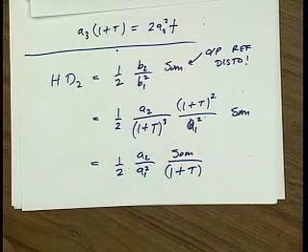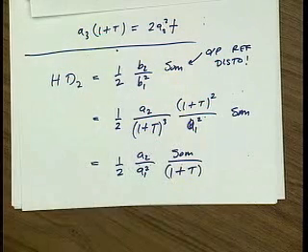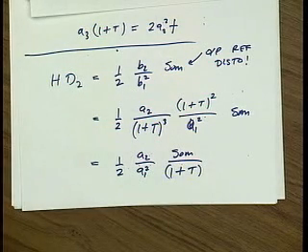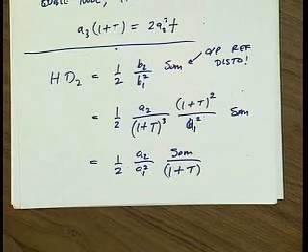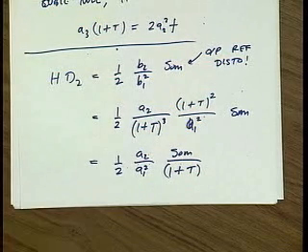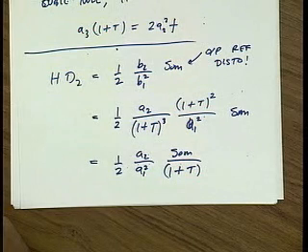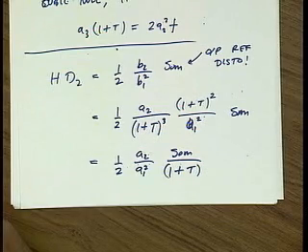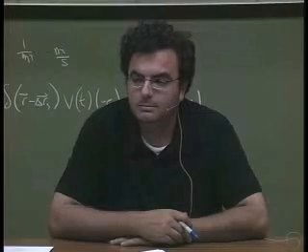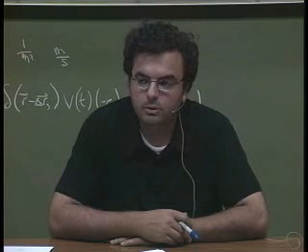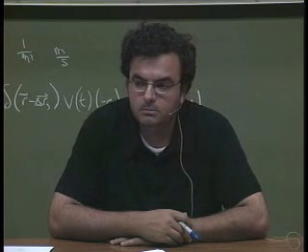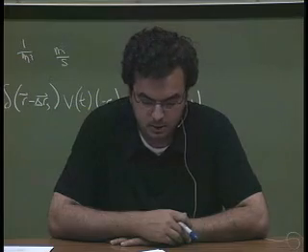But I don't give myself that pleasure. I use the output referred distortion. Why is that the case? Anybody? Are you guys shy today? When it comes to the end of the day, all we care about is the output of our amplifier. If our output signal is shrunk, we might as well have HD3 shrink as well. Yeah, I think you have it.